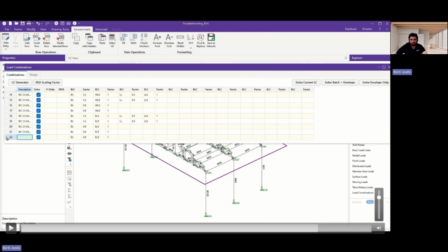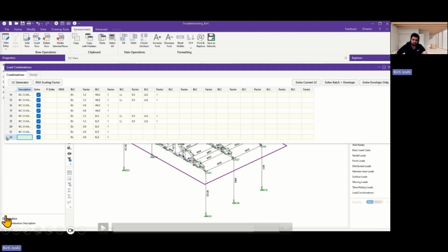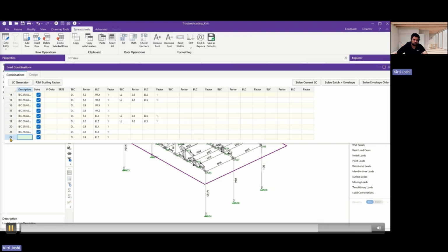In order to do this, you can simply nest your load combinations. Or maybe you have a model that needs to combine the effect of the static and the moving load, but because of the space limitation in the spreadsheet, it is impossible to fit them into one row. In that case, you may also use nesting load combinations.